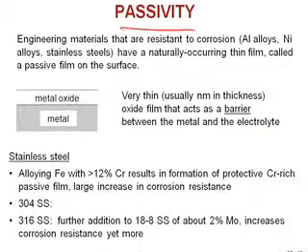It turns out that many important metals are resistant to corrosion because they're passive. We call them passive. What happens is they form a very thin oxide film, usually nanometers in thickness, on their surface that protects them from the external environment. So we have an aggressive environment out here, but this thin oxide layer that forms spontaneously, naturally, just upon exposure to air, forms on that surface and creates a barrier and protects it.